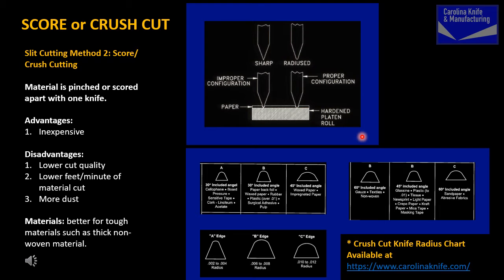Make them sharper. Another important thing to remember in score slitting is to keep your bottom anvil clear of grooves. Score cutting will wear a groove naturally in the sleeves over time as you have steel-on-steel contact. When that happens, simply move your cutting tip to another part of the sleeve.